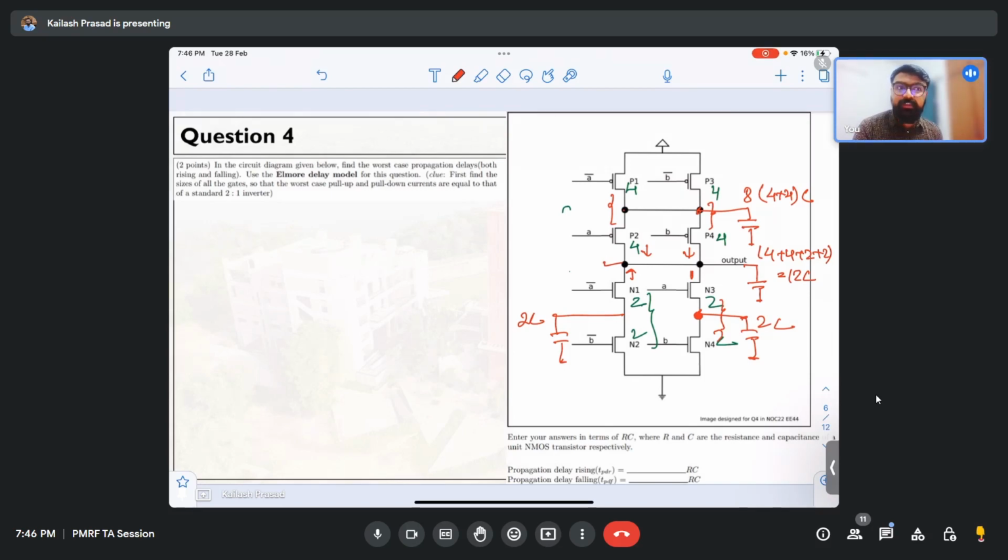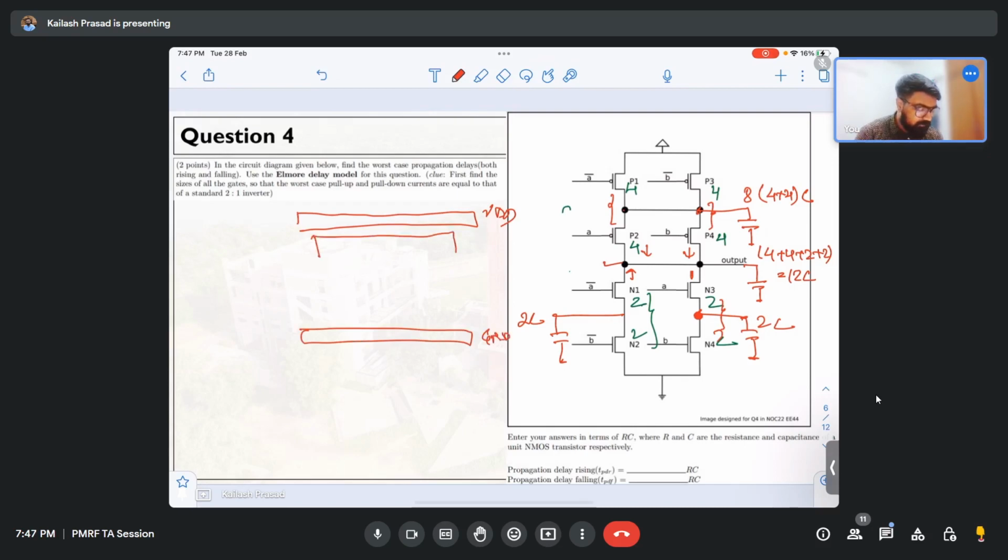So whenever you design the layout, how do you layout? Generally, they are designed like this. Here it will be VDD, there it will be ground. All the PMOSes will be sitting here, and all the NMOSes will be sitting over here, and all the connections you will make like this. So PMOS and NMOS are not sitting together, so you cannot diffuse. That's the rule that has been imposed on the standard cell layout, and that is the reason why we cannot diffuse that.